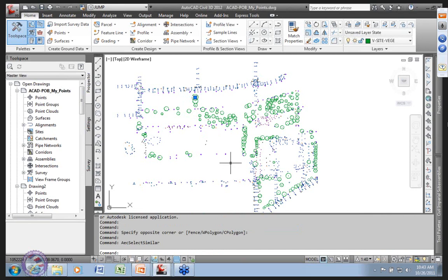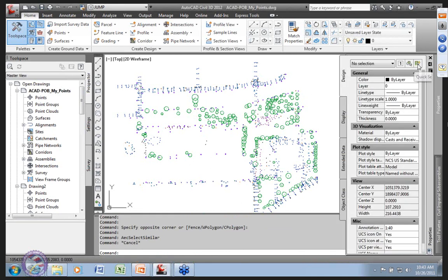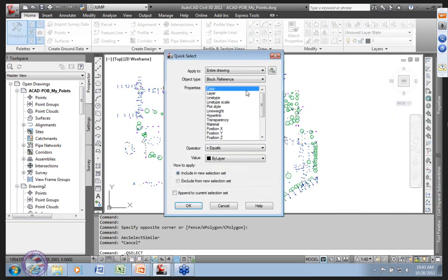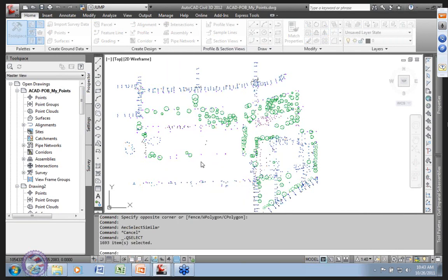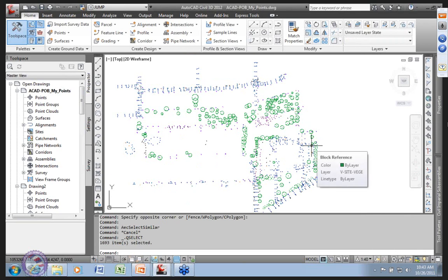And it gives you a big, huge pile, right? Did that select all that stuff? Wait a minute. Okay, another way to do this, hey, we're in AutoCAD, right? I want everything called the block reference. Grab them all. Please include the selection set. Grab all those things. Make sure I got every single little teeny bit and piece. No windows involved. And now that I got them, I simply want to explode them.